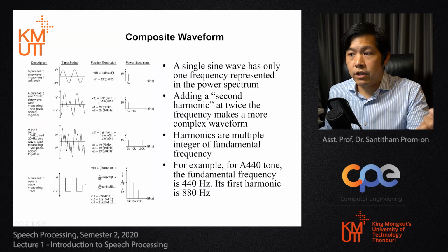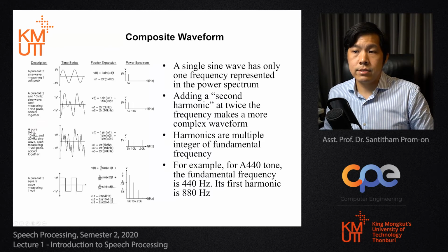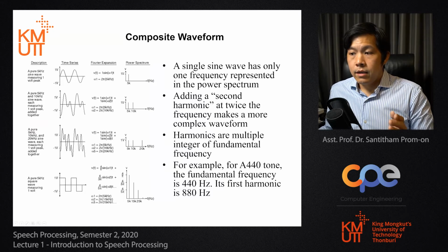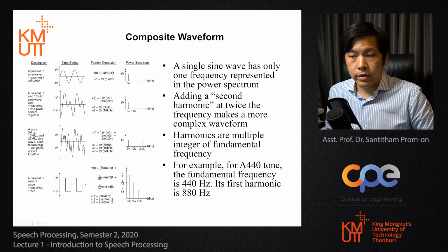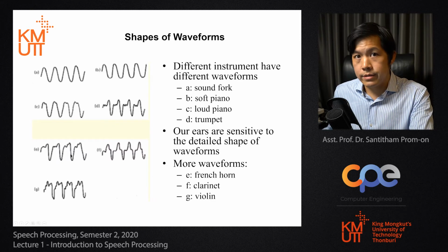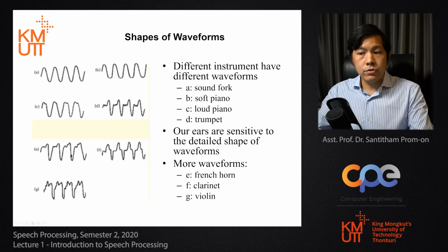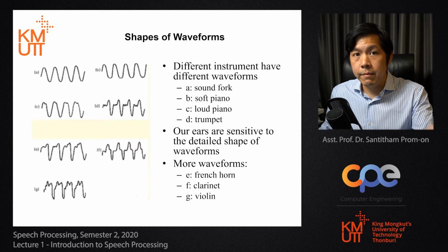The first function is at 5K, the second at 10K. Combine them, and you get a sound like this one. With three frequencies, 5K, 10K, and 20K, you get the time domain like this one. You can see that this one is actually quite like the one down here, right? So it means that we can decompose the signal here into multiple sinusoidals and analyze them.